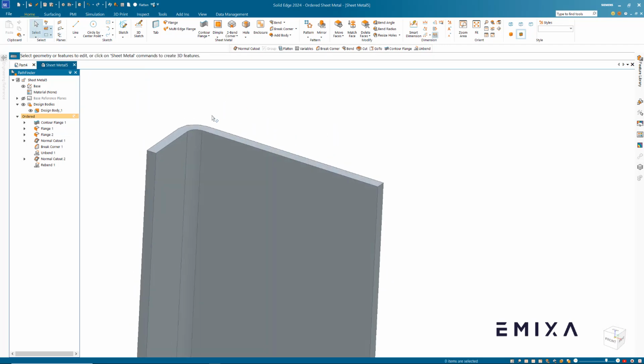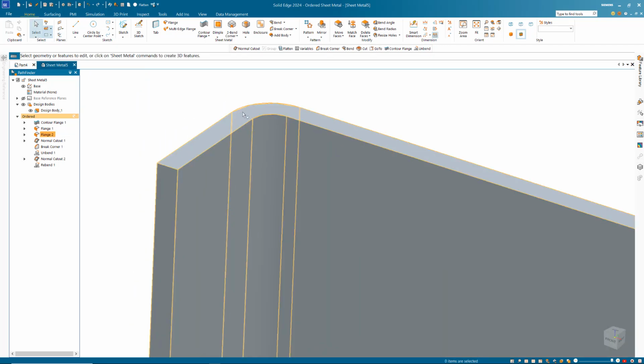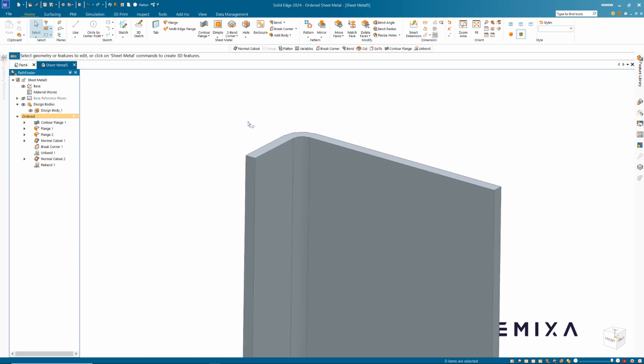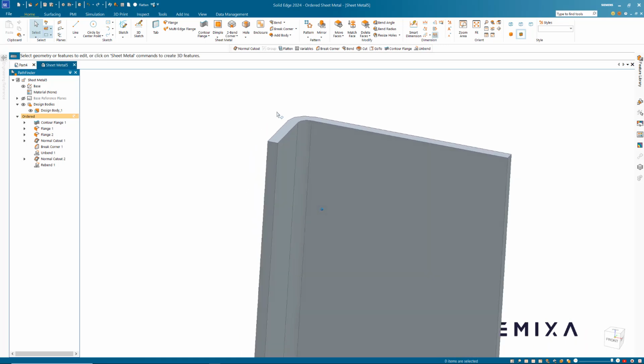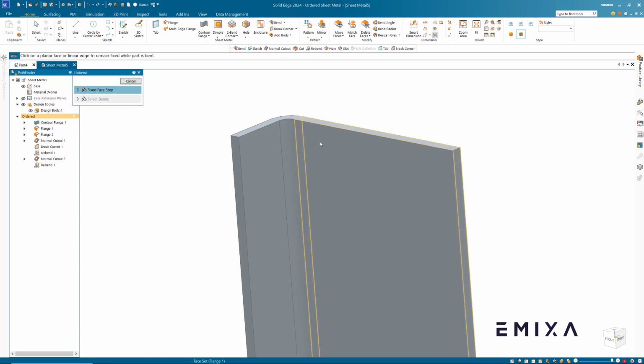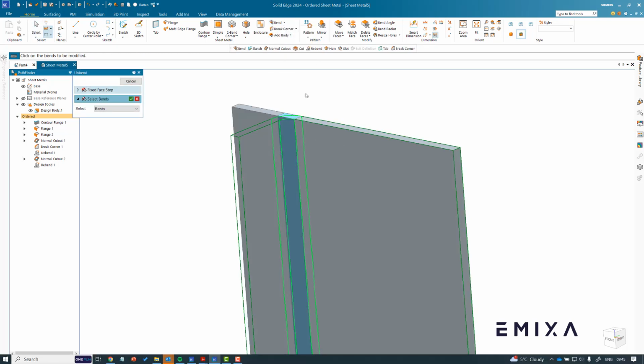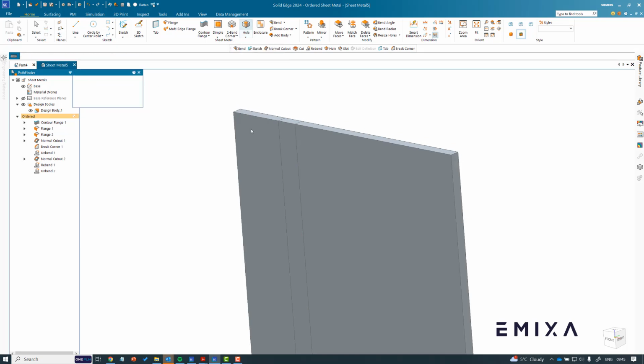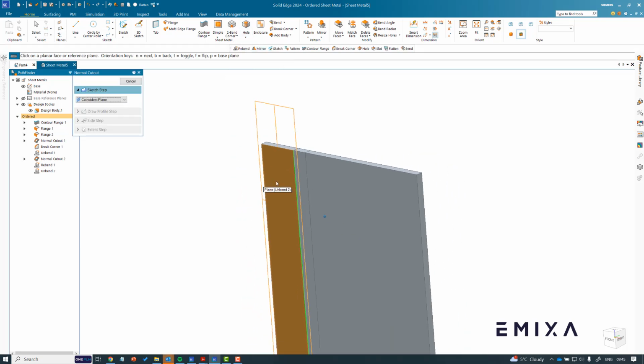We've got something similar up here. We need this little section of face to be 2mm down from what we've got. So we're going to do something similar here. I'm going to do an unbend again. So click the bend to stay, the bend we want to unbend, and then accept. And then we're going to do a normal cutout. I'm going to do that on this face.